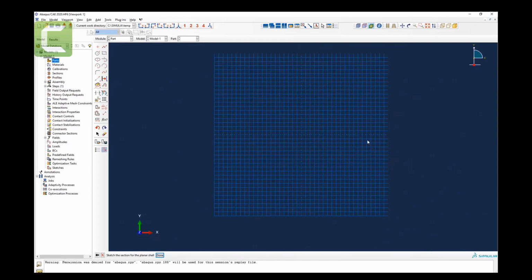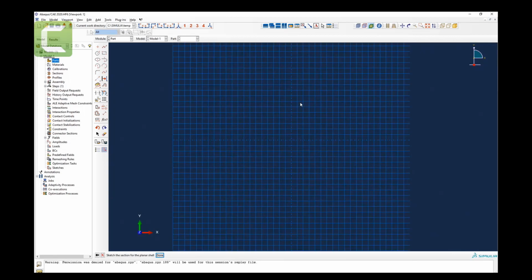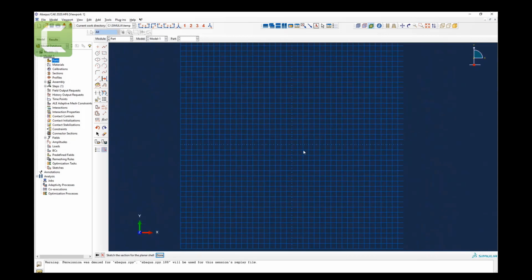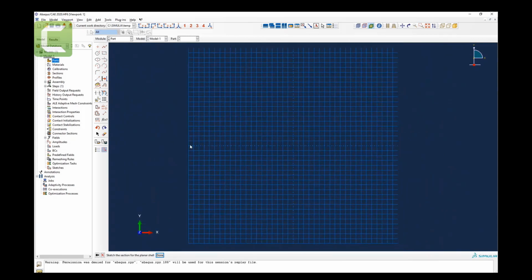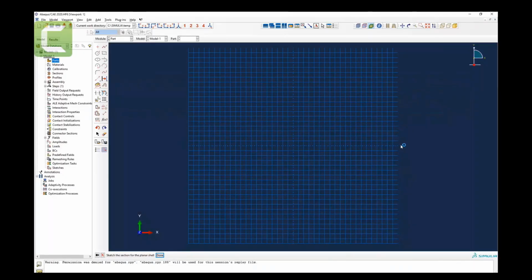Now, as I mentioned, sheet size is 4000. So that is 0,0 here. This is a coordinate. If you used AutoCAD or something in your previous undergraduate degree, that would be useful. So 0,0 here. Now I put 4000, meaning that from this line to this line is 4000, and this is 0. So minus 2000 goes this way and another 2000 goes this way, so total 4000. That's the sheet size that I put in the previous window. You remember that one right here? I put 2000 here. It means that from this point to this point is 2000, and 0 in the middle.